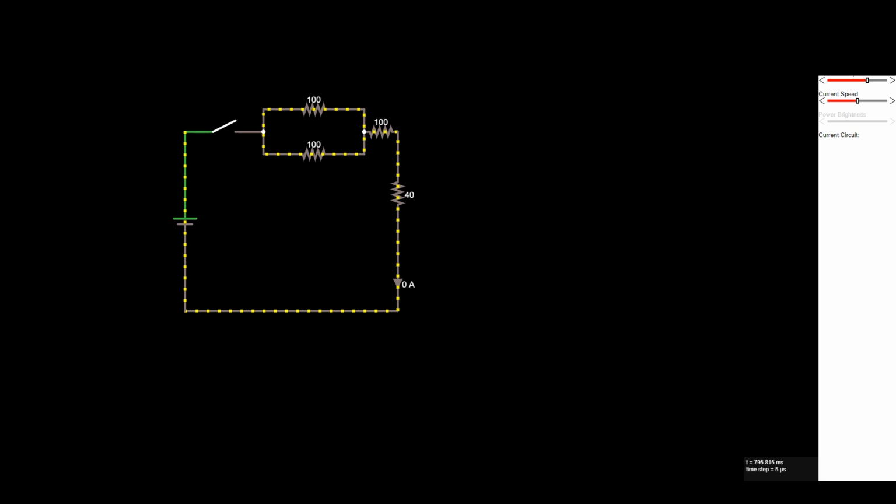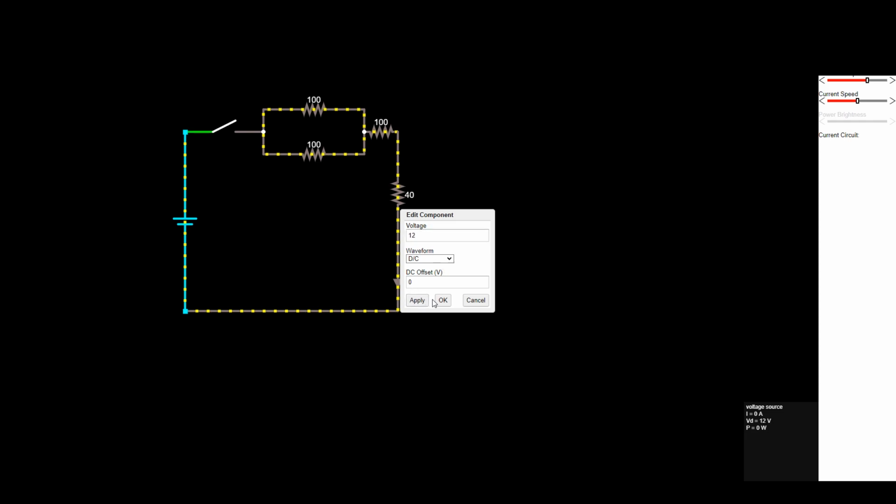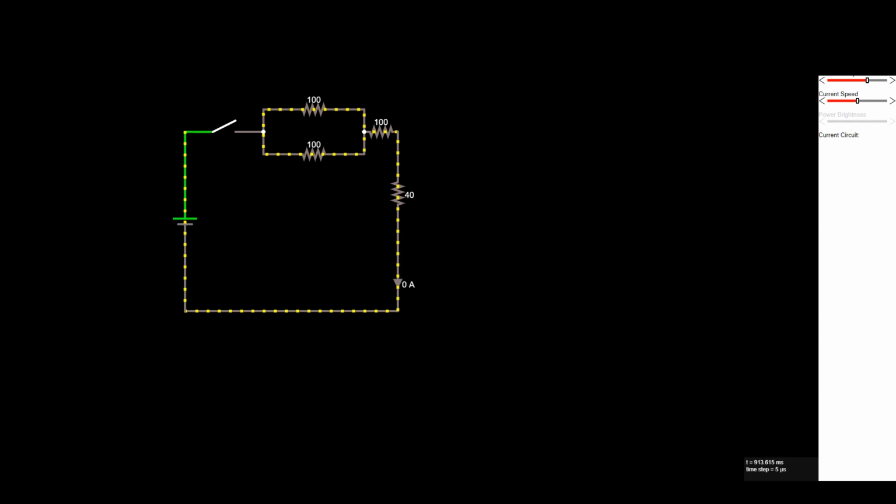In this simulation, first we set the voltage to 12 volt. Then we can see the arrangement of the resistor as we chose before, and after all the setup we close the switch. The value the ammeter measures is 63.158 milliampere, so we can put that value into table 3.